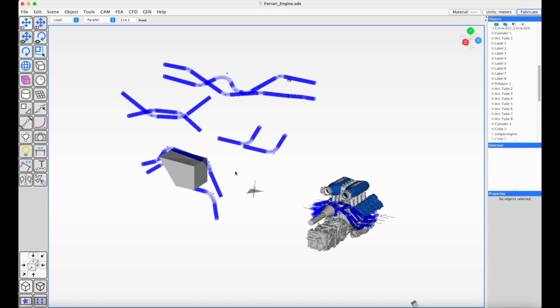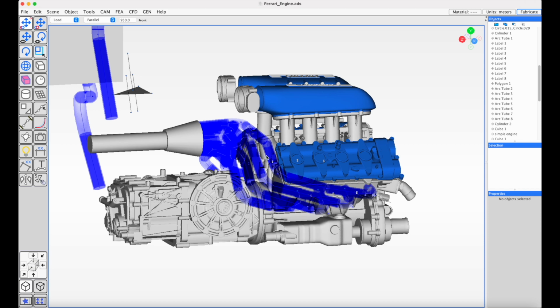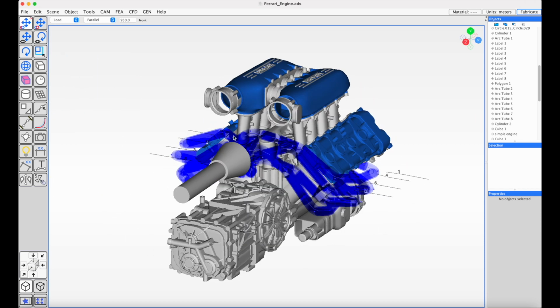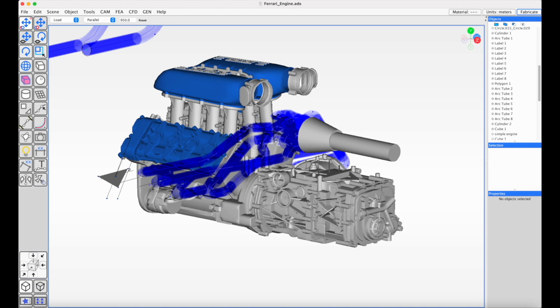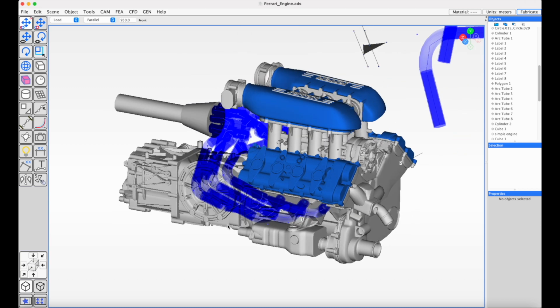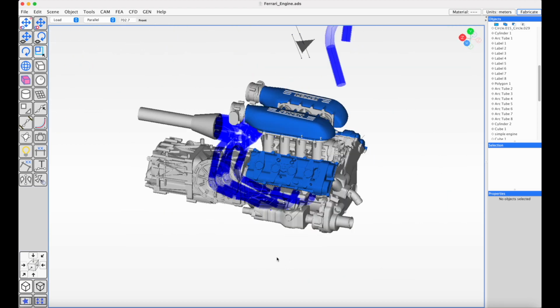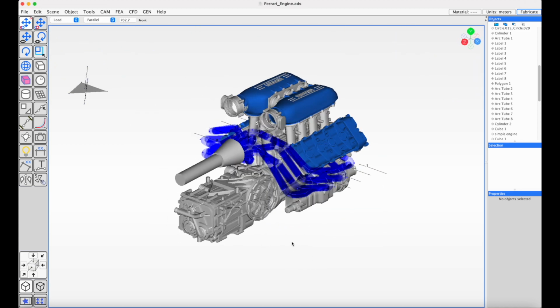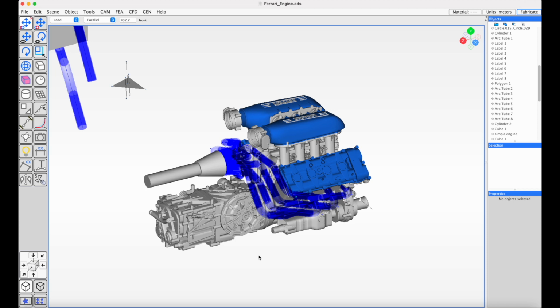So the use case for this is going to be you scan, 3D scan, or import an object of the application that you want to design tubing for. You define the endpoints, so the start and stop points, and you basically run a draft version of the tubing where you think it could go roughly, and then you let the machine run, and it's going to experiment with a whole bunch of different avenues trying to optimize for the criteria that you're looking for. So it may take an hour, or depending on the compute available, it may take more or less,